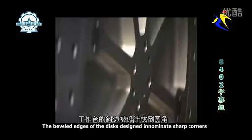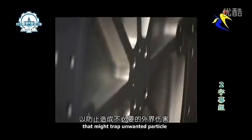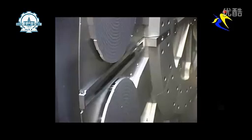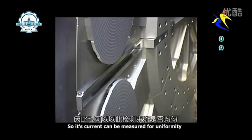The beveled edges of the disc's design eliminate sharp corners that might trap unwanted particles. Encased channels use water to keep the wafers cool. A slot on the disc allows a sampling of the beam to come through so its current can be measured for uniformity.